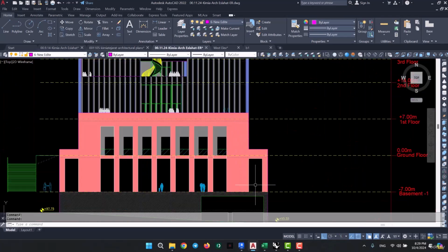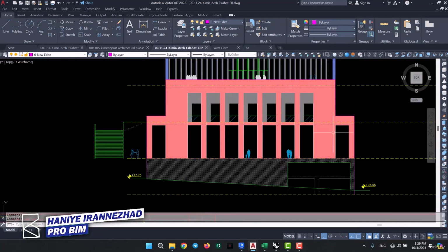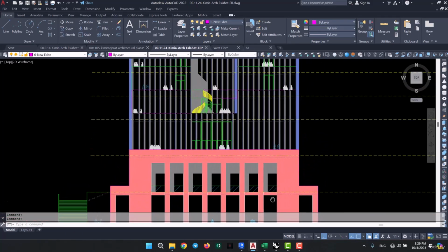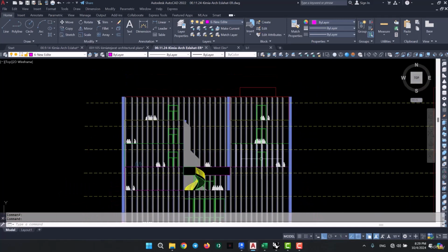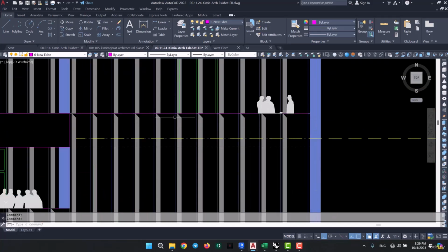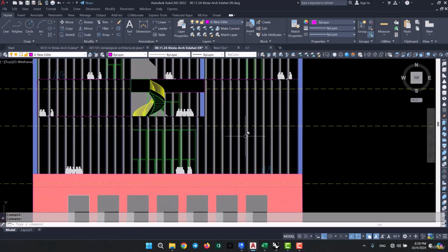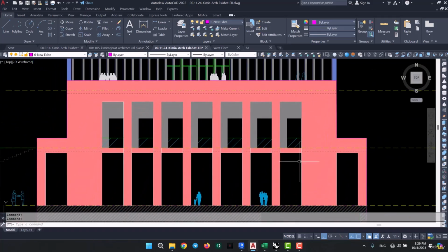Now let's talk about this part of the exterior. So that would be the south side, and then there's this wall over on this part. Basically, we want to figure out what is the best way of modeling this in Revit. We've already gone through the upper sides in the previous videos, so there's nothing too crazy. It's all just the same terraces, for which you're going to have to draw the curtain walls just like we discussed before, then readjust their elevations. But as for this part at the bottom, we're going to practice it together.